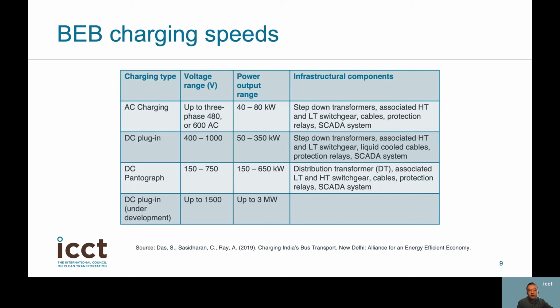An industrial consortium named Charging Interface Initiative's High Power Commercial Vehicle Charging Task Force is developing high power charging tailored for commercial vehicles that can achieve a charging capacity of 1 to 3 megawatts. This technology is still in progress, but would make charging larger batteries onboard commercial vehicles like electric buses a much faster process. Rates of charging may affect battery durability for certain types of battery chemistries, so when planning for infrastructure, compatibility with buses needs to be considered.